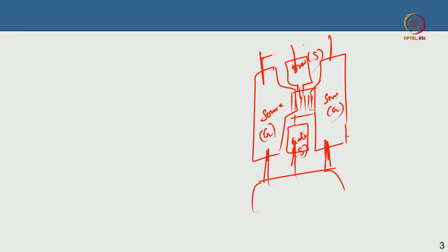This is like a coplanar waveguide, and this is very common, very popular. It's very easy to use, especially for compound semiconductor based devices. This is very widely used, and when you have this kind of an arrangement to measure the S parameters, for instance, you can do pulsed IV measurements. I'll come to that. Then there is load pull to measure large signal behavior of the device. Okay, when I say large signal, I'm talking about nonlinear.